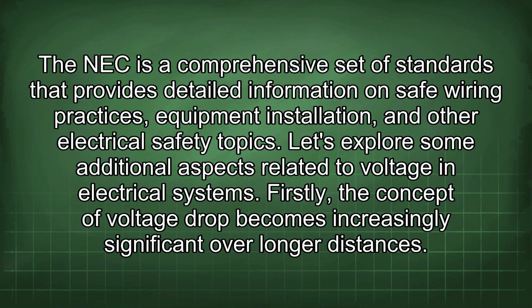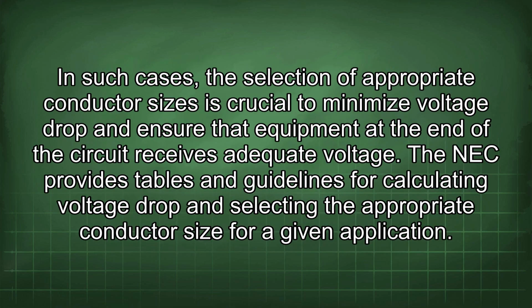Firstly, the concept of voltage drop becomes increasingly significant over longer distances. In such cases, the selection of appropriate conductor sizes is crucial to minimize voltage drop and ensure that equipment at the end of the circuit receives adequate voltage. The NEC provides tables and guidelines for calculating voltage drop and selecting the appropriate conductor size for a given application.